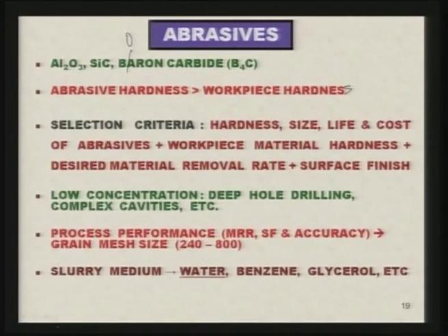The slurry medium, or the abrasive carrying medium, normally selected is either water, benzene, glycerol, etc. Especially a low viscosity liquid like water is recommended, so that it can reach fine details or complicated shapes easily.